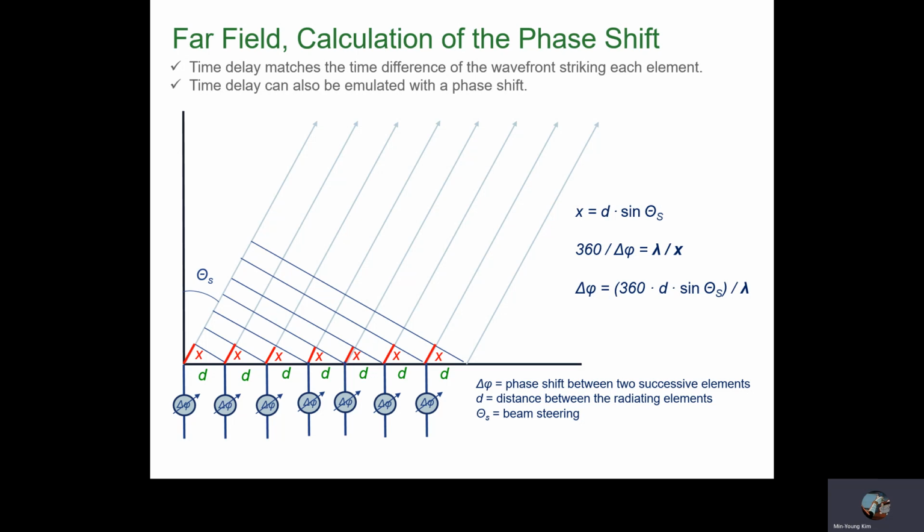Beam steering is achieved by changing the phase of the input signal on a radiating element. Phase shifting allows the signal to be targeted at a specific receiver. This engineering slide might be very difficult to understand in a short time, so just remember the major key parameters which control the beamforming. Pi is how much phase is shifted between two element signals, and zeta is the overall beam steering angle.